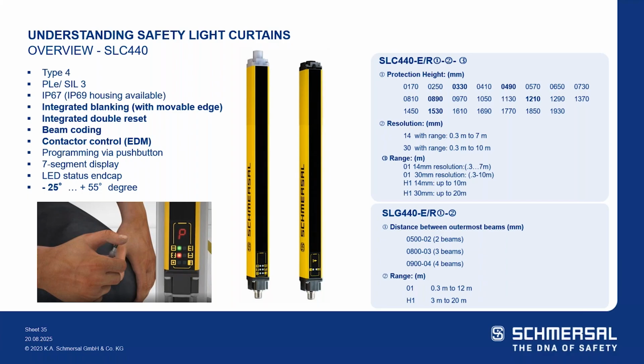Minus 25 degrees upwards to plus 25 degrees for your ambient temperature area. Your protected height on the safety light curtain SLC 440 series goes from 170 millimeters up to 1930 millimeters. Again, with your 14 mil resolution or your 30 millimeter resolution, so finger or hand. 7 meters to 10 meters is your standard range, and we have high range. We even include the high range on the 14 millimeter resolution up to 10 meters, and for the 30 millimeter resolution up to 20 meters.